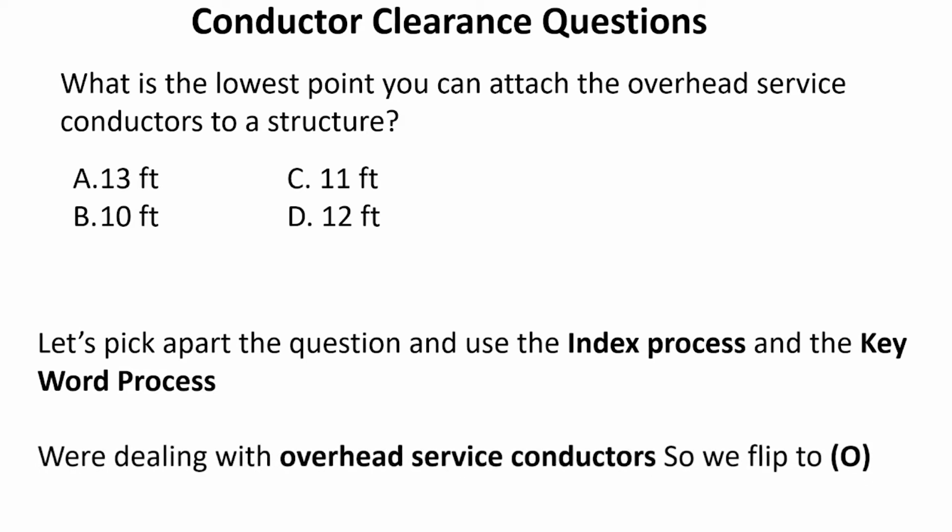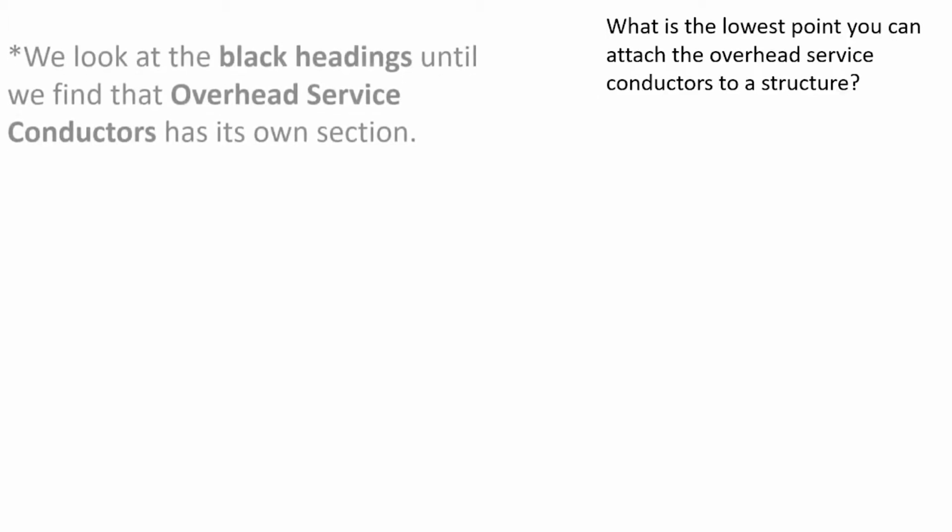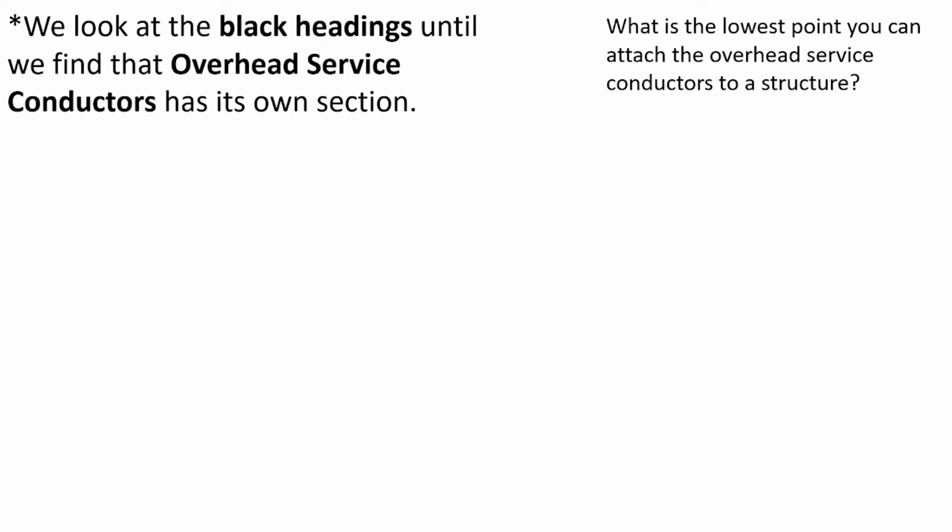We're dealing with overhead service conductors, so let's flip to O in our index and see if there is even a section called overhead service conductors. If not, we'll switch gears, but first always start with the most obvious. Okay, so we look at the black bold headings until we find overhead service conductors. It has its own section.